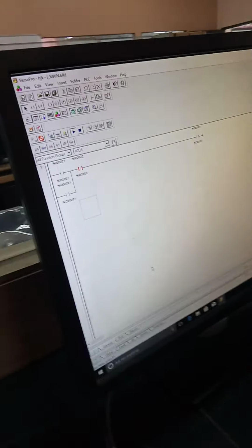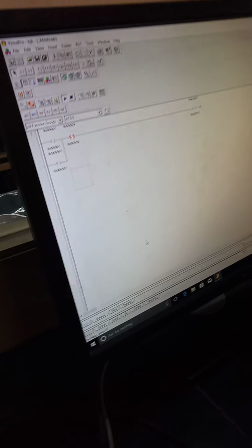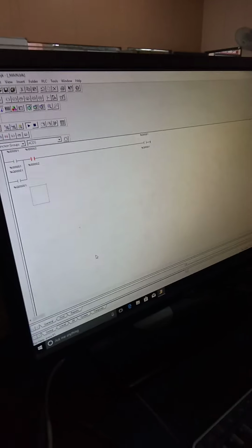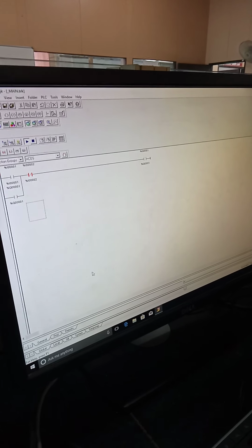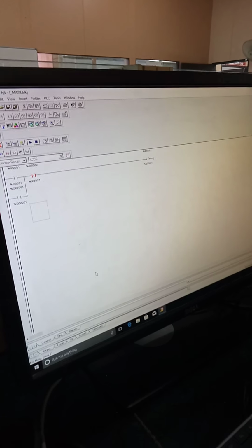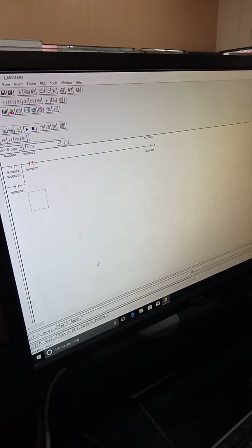So this is about the basics of PLC. In this we have discussed normal operation of input and output, PLC ladder programming, logic gates and motor latching circuits. All those things we have done. In the next two exercises we will see timer and counter in one exercise, and then automatic actuation of a double acting cylinder using a solenoid in another exercise. Thank you.